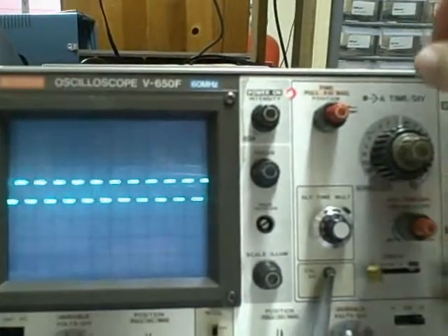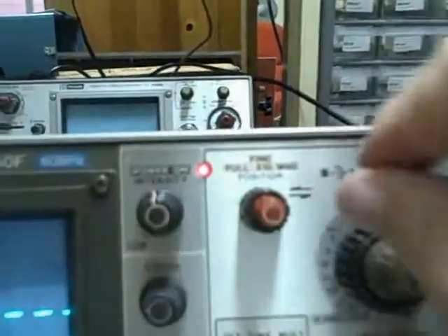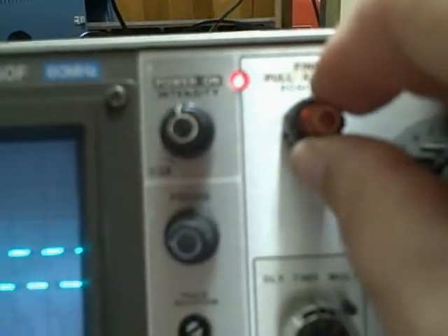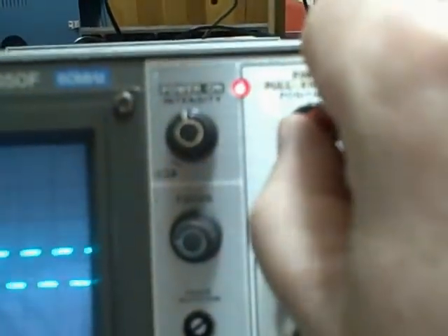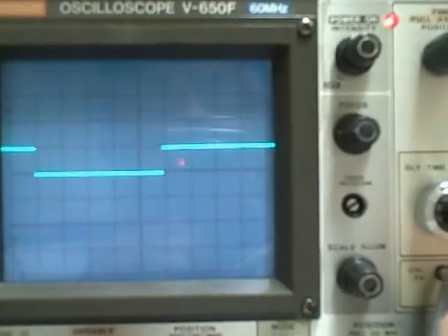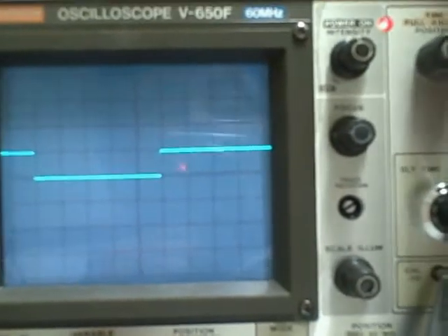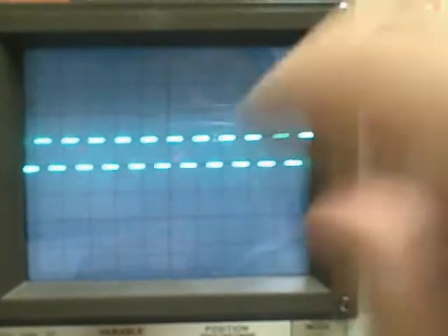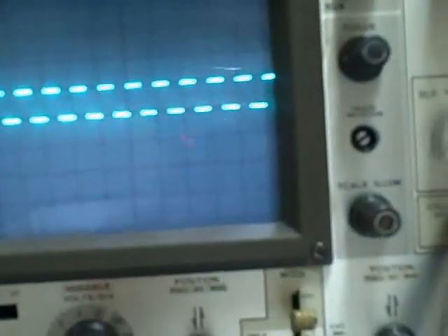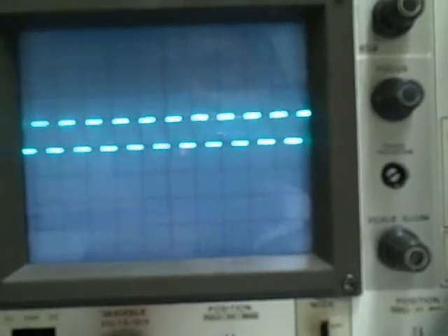One of the other functions of the scope is that we have a times 10 magnifying position, and if I pull, then we display our signal time base wise times 10. Here we are running approximately 1 cycle per division, and that's at 1 millisecond, so we're running about 1,000 hertz.